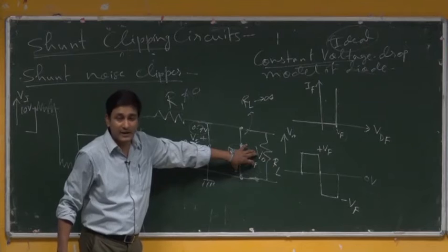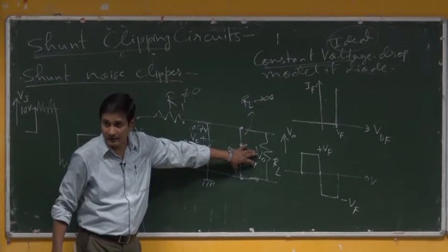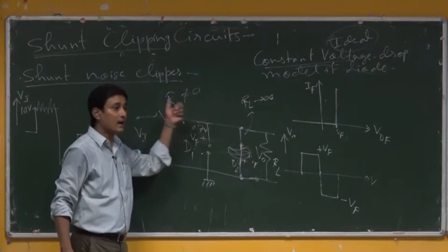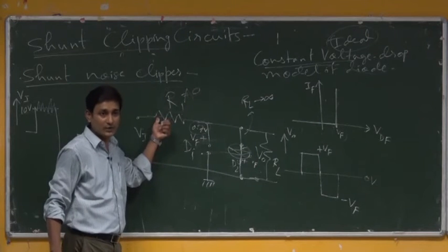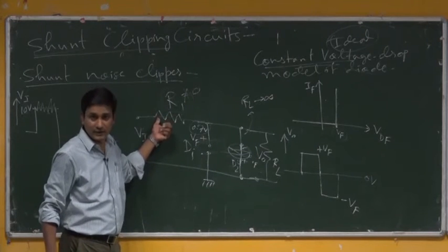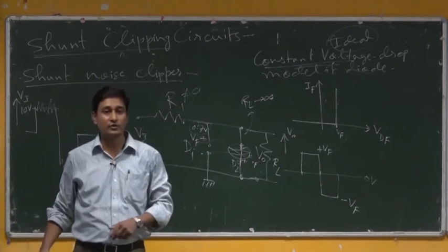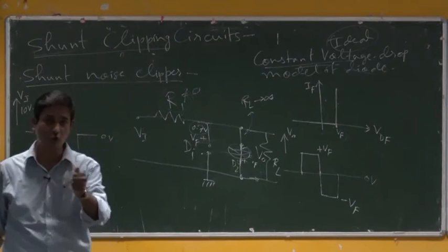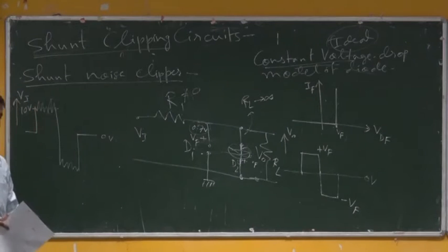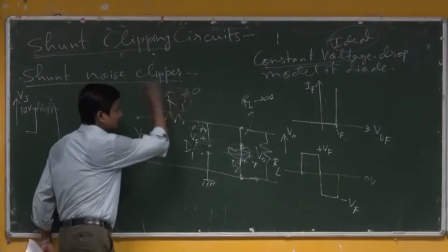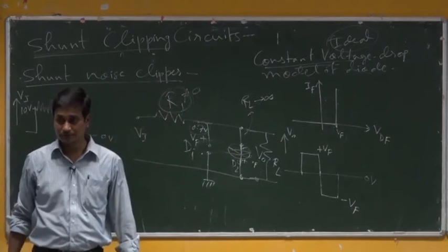That means the maximum current that can be allowed through the diode. Depending on that, this resistance R1 in series to the diode will be decided, so that even though the diode is at 0 volt, still the current flows through it in a controlled manner. Okay. So, that is why in this circuitry also we are always considering R1 non-zero.